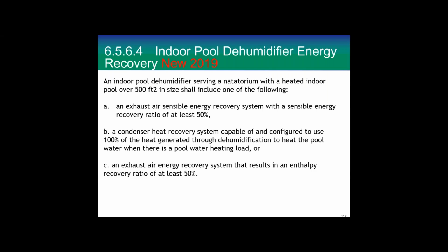So it's exhaust energy recovery for the pool, and also a condenser heat recovery system capable of 100% recovery through the dehumidification to heat the pool water when there are pool water heating loads. So it's the air side and the condenser side of the equipment.